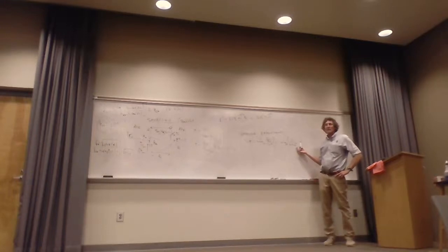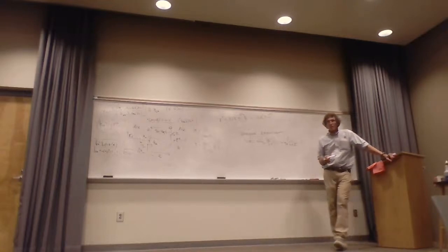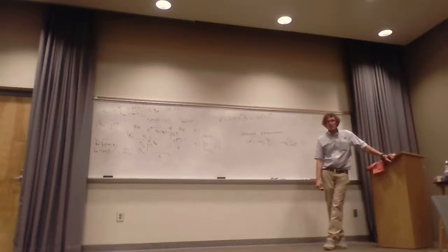If this number is 10 to the 4th, the log of 10 to the 4th is 4, and 4 times 20 is 80. If it's 10 to the 5th, the log is 5, and 5 times 20 is 100 dB. Shielding effectivenesses of over 100 dB are probably very reasonable for a lot of shields.